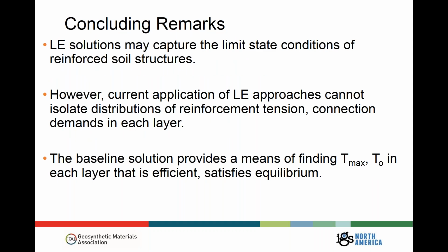Limit equilibrium solutions may capture the limit state conditions for reinforced soil structures. That's been shown before. However, the current way we apply it can't give us all the information that is frankly useful. It can't give us distributions of reinforcement tensions and demands in each layer. And with the baseline solution, we can do that.